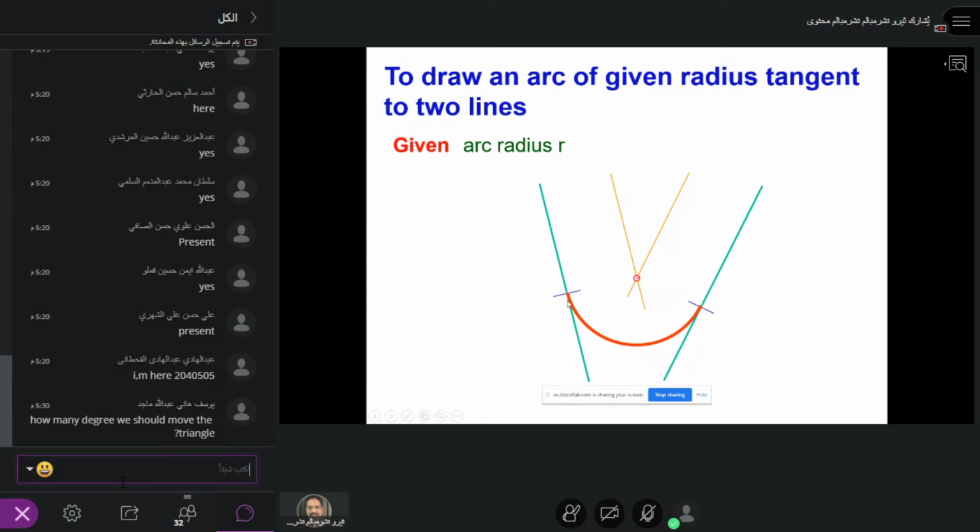All right. Now he makes an arc for an angular section. So what he did, in order to understand this, they draw a parallel line by using the arc method. You take the radius arc and draw the tangent parallel to this. Similarly here, and then mark the center point, and the starting point will be a perpendicular line to this point for both lines, and then take this as the center and this as the radius and starting point to the finish point. They will make an arc. This is your exercise today, so you should be very clear about that. All clear? This is your exercise. You have to make it today.